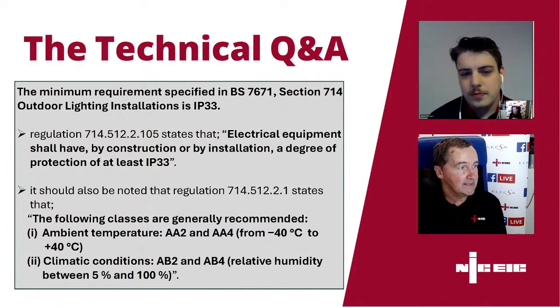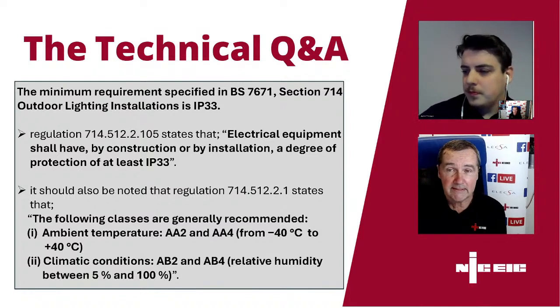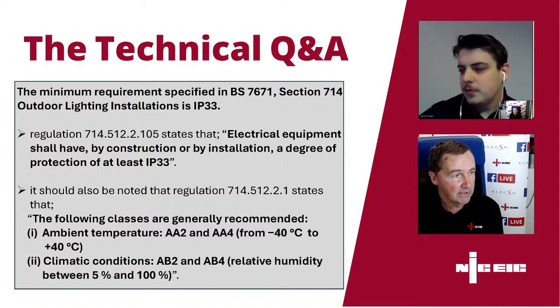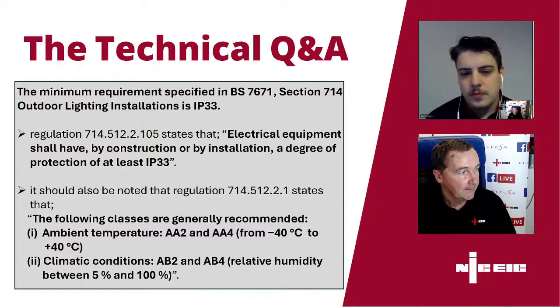Well, the doubling is a rough rule of thumb. It's not quite doubling actually if you do the maths fully. But doubling 4.6, even if we do it by 1.7, you're probably still going to be greater than 6 kA. So yeah, we would certainly recommend upgrading to 10 kA, just so that you've got devices that will withstand that prospective fault current and still be able to operate again if there is a further current after they've been reset.